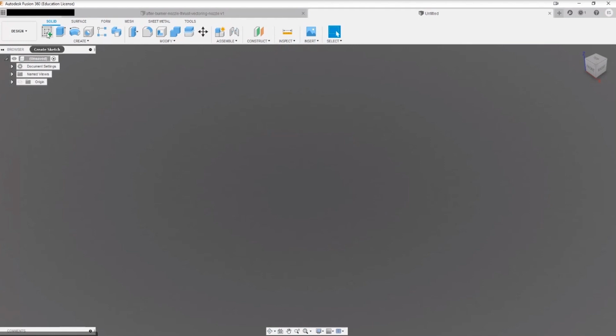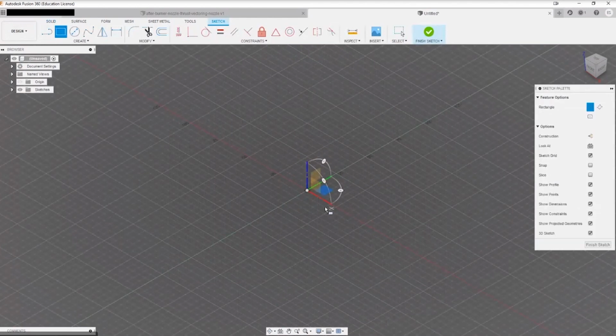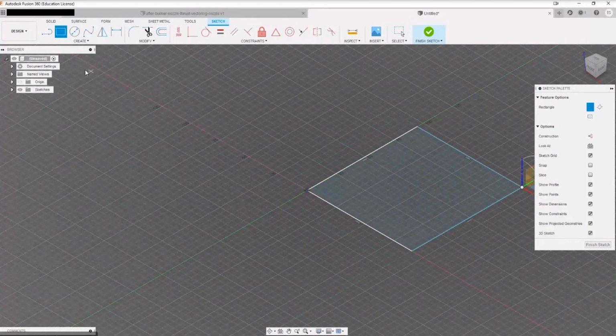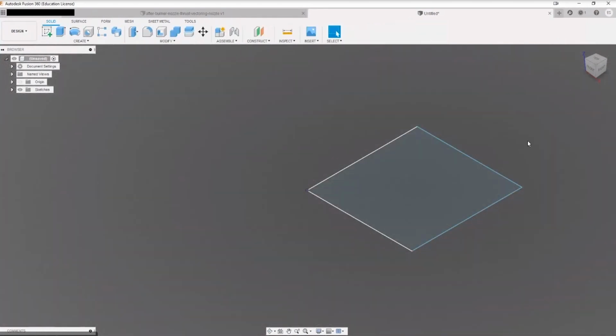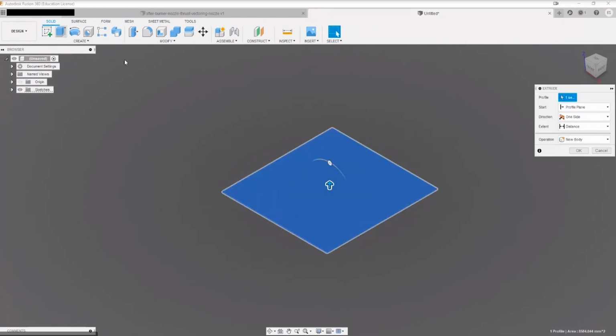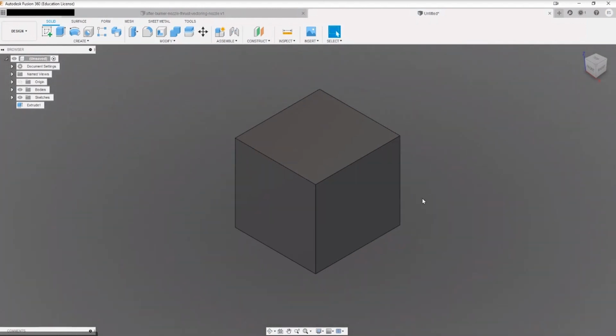And secondly, it'll spare you quite a lot of pain with the actual model that you're trying to create. So we're going to open up a sketch here. New sketch, we'll pick an axis. Now, what you can see here is if I just create a sketch, just a random square, I can click on that, hit extrude, and bring it up. Great. So now we've got this volume.